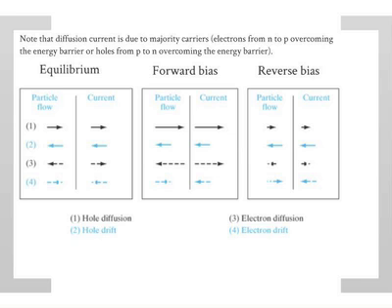That's why the diffusion and drift are balanced under equilibrium. But now we have shifted the equilibrium, so some holes are able to get across. So imagine the holes got across. So there is no field outside. That's the assumption. Once they have crossed that energy barrier, you reduce the energy barrier, so many holes have gone across. So what happens when they get to the N side?